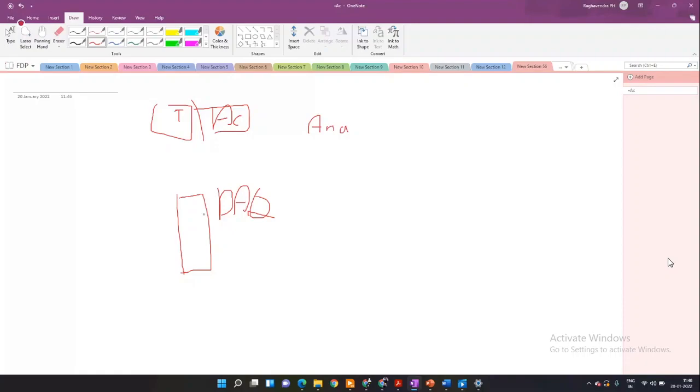So you have DAQs that are capable of receiving analog signals, that is analog input DAQs. You have analog output DAQs. You have digital input DAQs, which take in data in the form of 0, 1, basically digital. And then you have digital output DAQs. So when I want to do a temperature and an accelerometer, I'll obviously need an analog input DAQ, because there is nothing that goes from the data acquisition device to your sensor. It is always from sensor to data acquisition device.